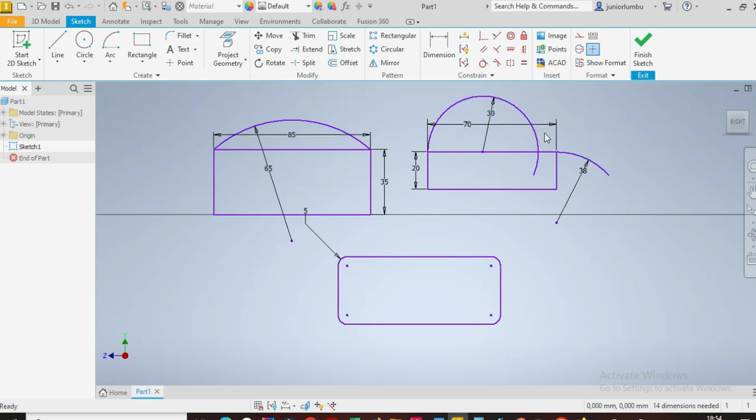In case you have two things touching each other, like here, where this line is crossing this other line, so the arc is crossing the line of my rectangle, to remove the part that I don't need, I'm gonna click on trim, then I'll remove that part, up to the next boundary of another drawing or another line or arc, wherever there is an intersection.